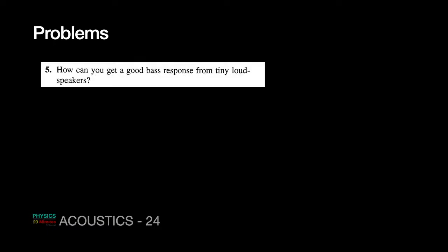How can you get a good bass response from tiny loudspeakers? Yes, there I'm going to talk a little bit. Remember, tiny loudspeakers definitely do not produce good bass. So in order to improve it, there are many things which can be done. For example, one company places its speaker in such a way that it fires all the sound energy towards the bottom side, that is, on the surface on which the speaker is kept. Say, on a table, the table surface becomes part of the speaker and produces a better bass effect. Similarly, some speakers are designed to be kept in the corner of a room, so they take the help of the two walls to create a greater depth in low frequency production.